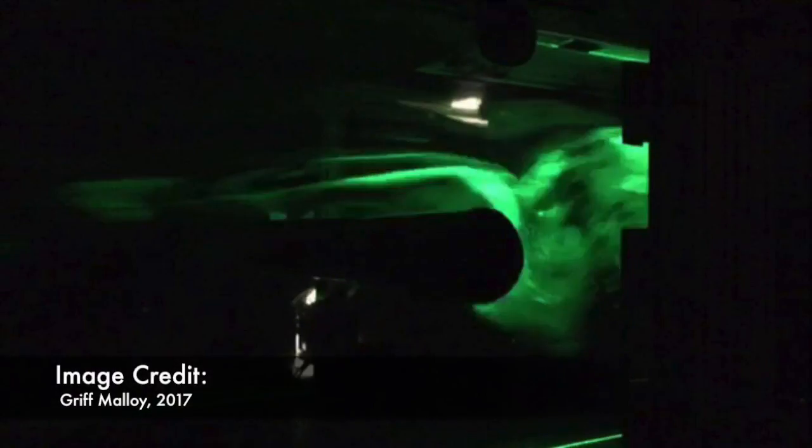Another group that had performed their experiment in the evening managed to use a green laser to illuminate the smoke in the wind tunnel flow and shared their images with us so that we could better illustrate the vortex shedding phenomenon at slightly different testing conditions. Although the image resolution is not very high, the individual vortices can still be seen off of the trailing edge of the cylinder.